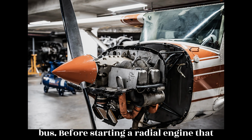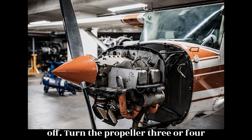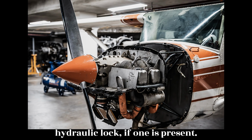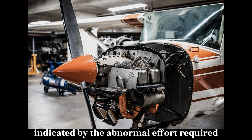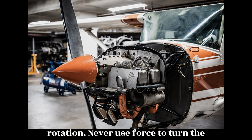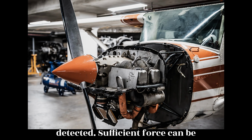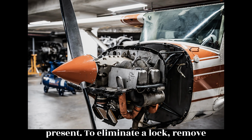Before starting a radial engine that has been shut down for more than 30 minutes, check the ignition switch for off. Turn the propeller 3 or 4 complete revolutions by hand to detect a hydraulic lock, if one is present. Any liquid present in a cylinder is indicated by the abnormal effort required to rotate the propeller or by the propeller stopping abruptly during rotation. Never use force to turn the propeller when a hydraulic lock is detected. Sufficient force can be exerted on the crankshaft to bend or break a connecting rod if a lock is present.